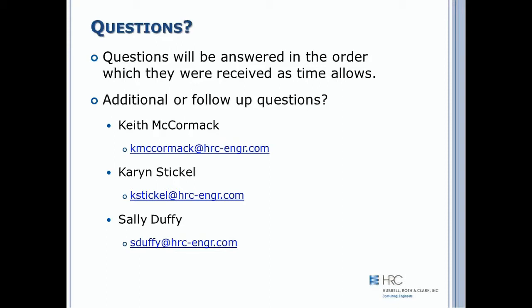But if you're not cleaning and televising, you can also make some assumptions about condition assessment based on, okay, we know that our concrete sewers built between these years tend to have more failures. You can do a more generalized assessment as well. But if you are including cleaning and televising in your grant application, you do need to use PACP certified personnel to determine the condition of the sewers.